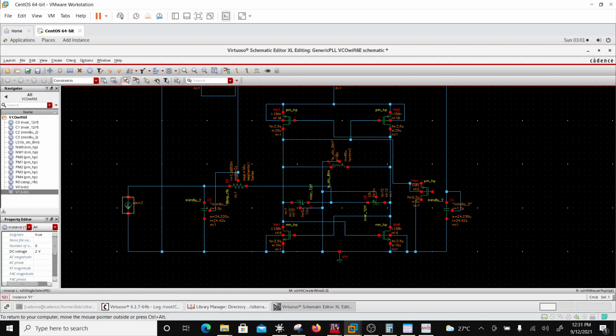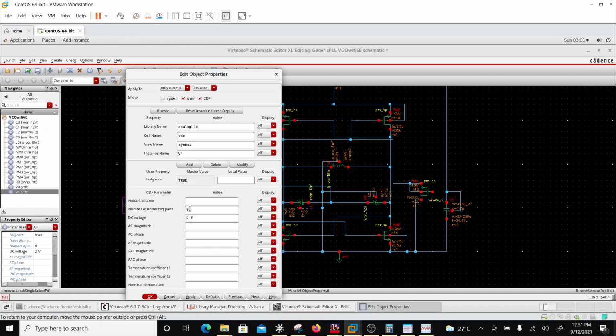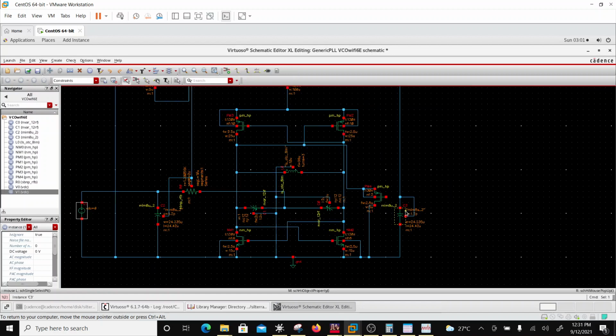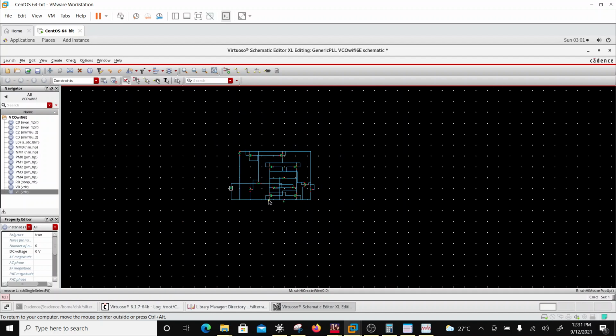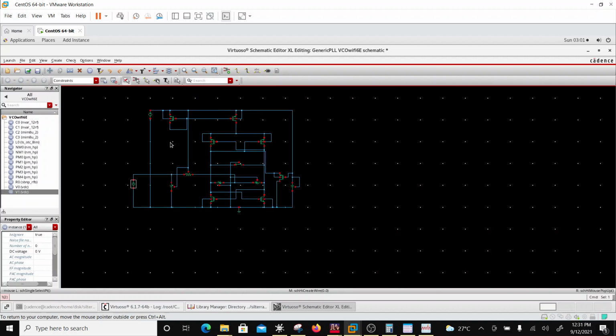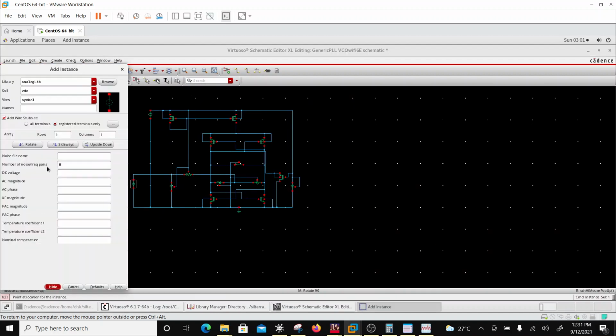And this control voltage I'm going to set as 0 volts. Okay, so with the voltages we are done. Of course, this will be connected here. Now we have to pull out a current. So IDC, again, of course there is a relationship between current also, so it's just not the loss. You can find in some classic books what the current should be. So I'm going to put here 300 microamps of current.